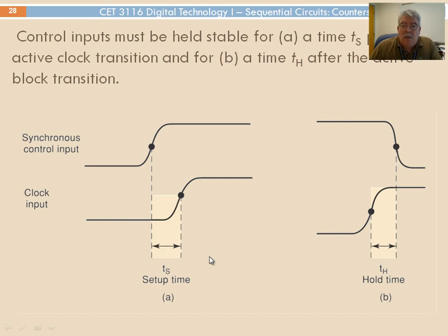That's what we call the setup time. And it is exactly the same for the hold time. So this is the clock. The clock is going up, and the input needs to be kept stable. So the setup time plus the hold time is the period during which the input needs to be stable to be read correctly.